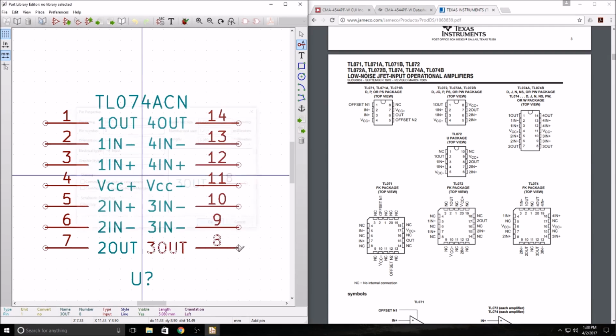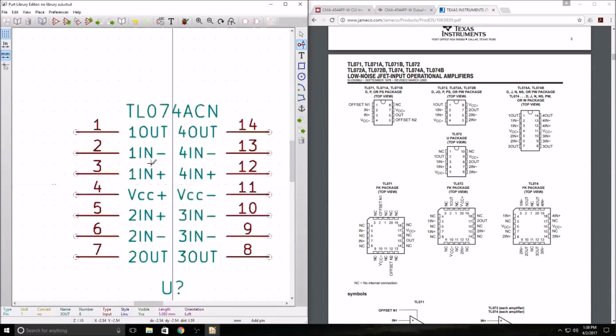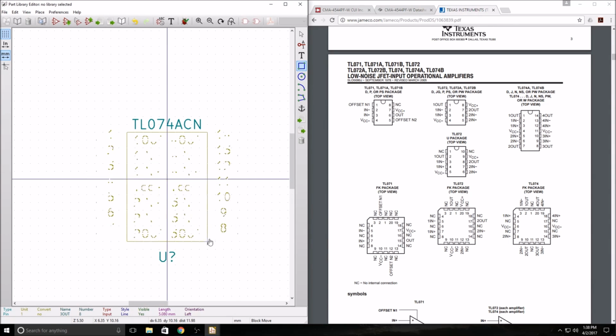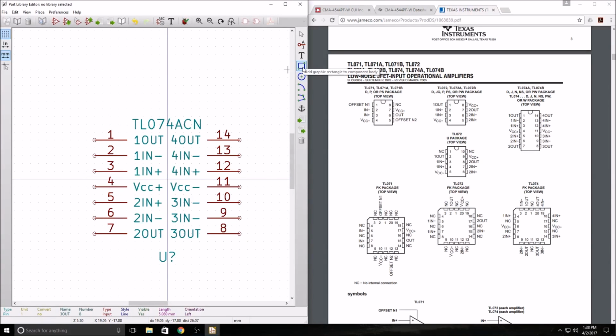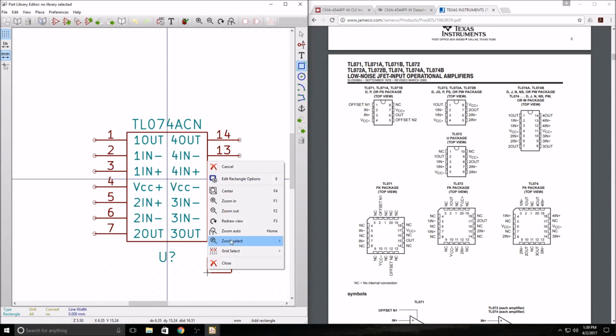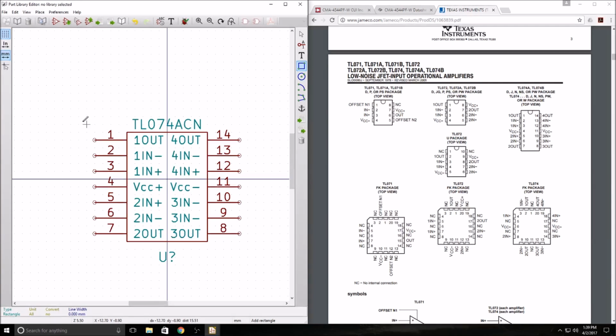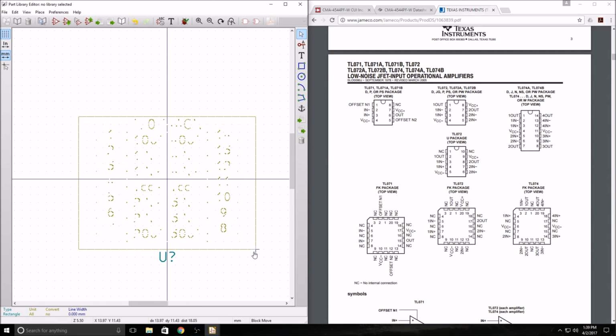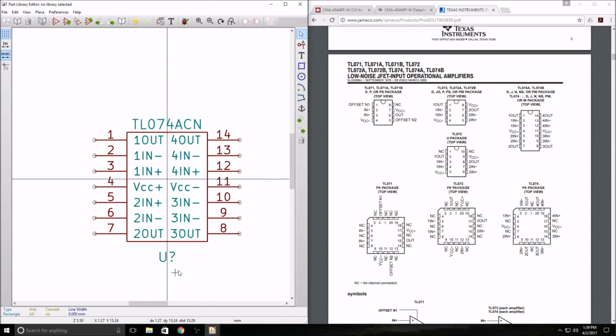Okay, now we've added all the pins that we want, and we are just going to make a very simple box outline to finish this shape off. So this just makes an, should add graphic. There we go. Okay, and hit cancel, and I'm just going to highlight this whole thing and move it down just a little bit so that at least it's somewhat centered on the center of this pin here. That's pretty good. Just move this up here.